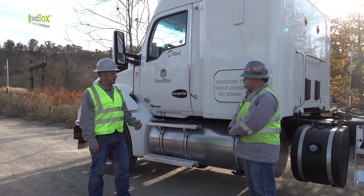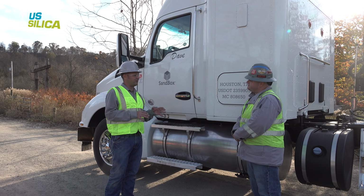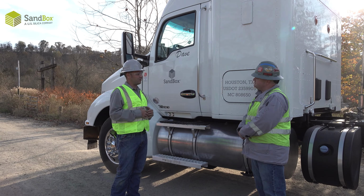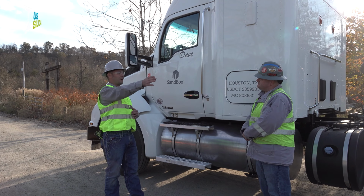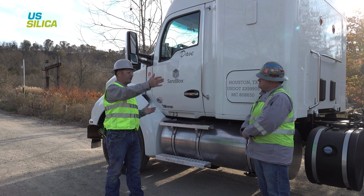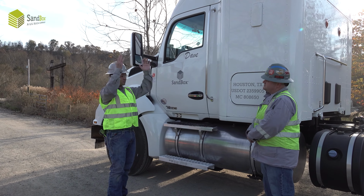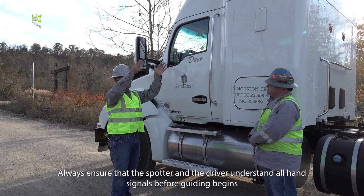Hey Dave, is this your first time at the location? Yes, sir. Awesome. Well, today on this particular site, they're requiring a spotter. So I wanted to go over the hand signals that we're going to be using to back you up into place here. So first off, I'm going to go back behind your truck about 45 to 60 feet. Once I get back there, I'm going to put my hands like this. This is going to mean to continue to come back straight.